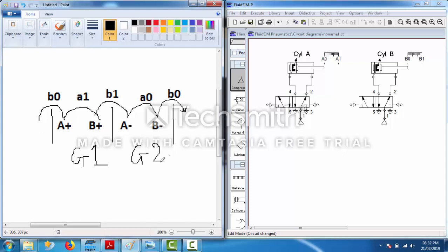Complete diagram. Now see what is the total number of sensors that we have used. 1 B0, 2 A1, 3 B1 and 4 A0. Then again B0 is repeated. So the total number of sensors used is 4. Now you can see that some of the sensors, for example B1 and B0, are changing group. Let us look at B1.